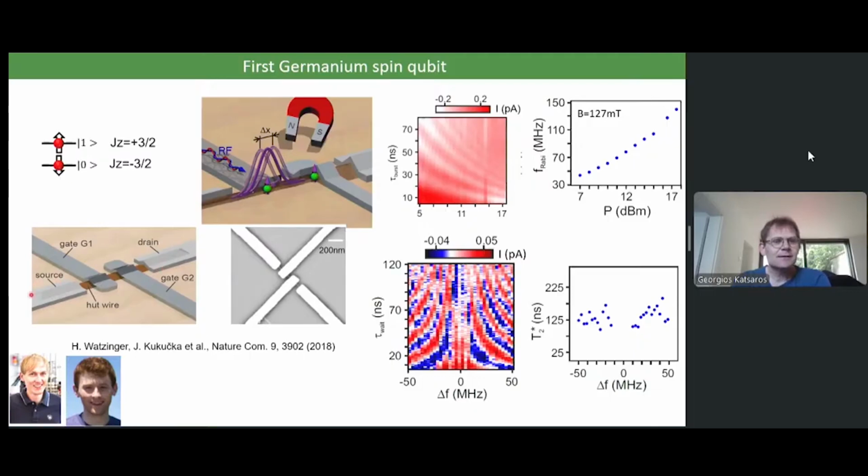What you see here are source and drain. These experiments were done in current, by doing current measurements. And what we found out that as these structures were so shallow, just by putting a gate on top, the strain creates a quantum dot below the gate. So here, just having two gates, we could create a double dot.